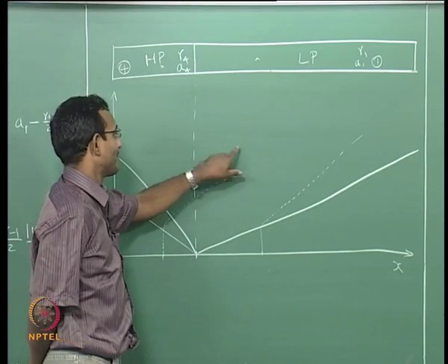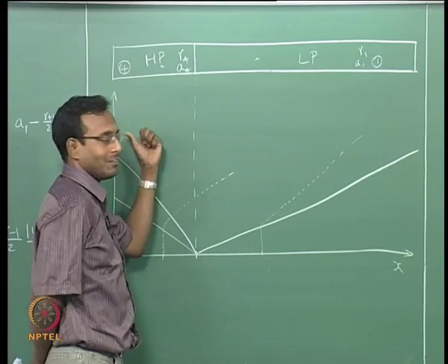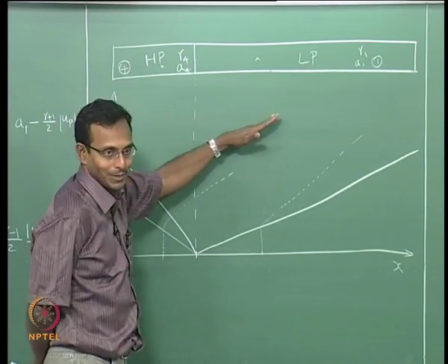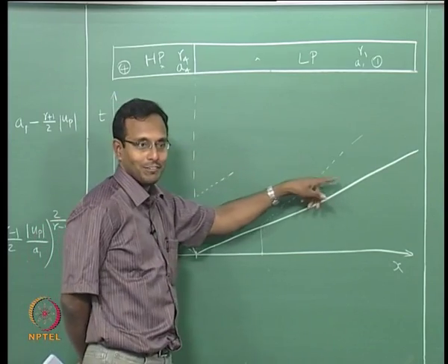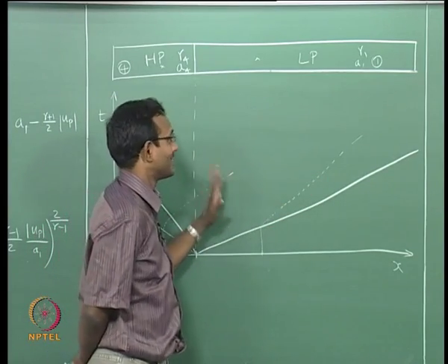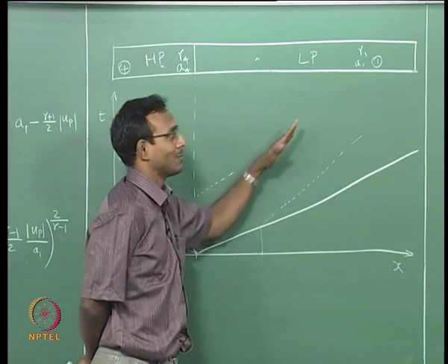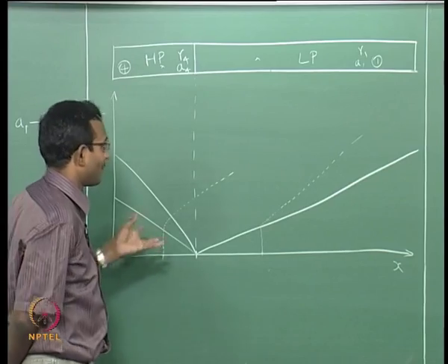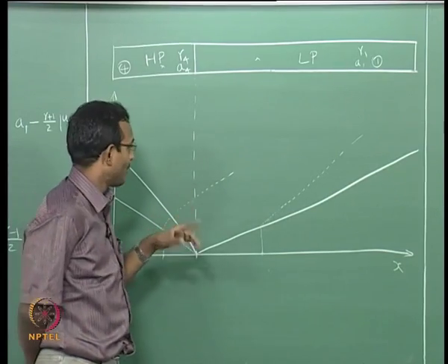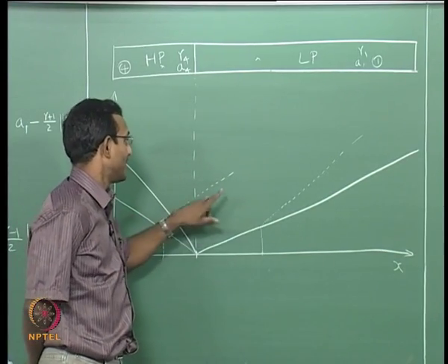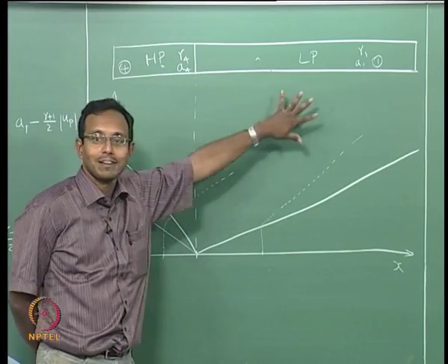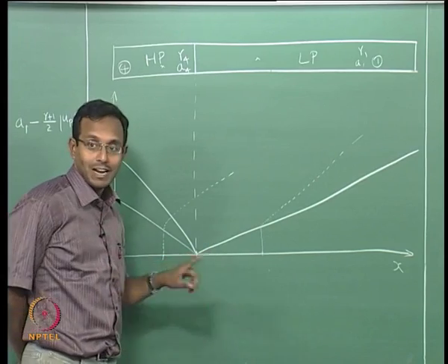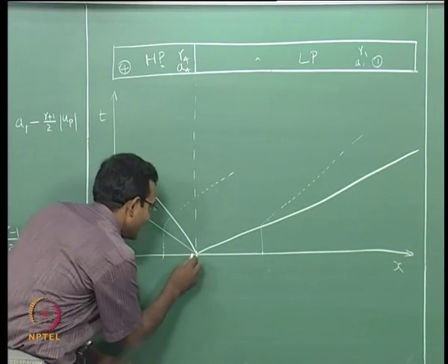Okay. Expansion fan from here going this way will tell the fluid to accelerate and fill that space, so the fluid will turn this way. Expansion fan going here will go and decrease the shock strength so that it does not go that far, but it will go a little more like this. So it will go to a point where it will finally have a nice equilibrium of these two velocities being exactly equal, that is, these two lines are parallel. Till that time it is not a stable system, and all this happens in this small region itself,